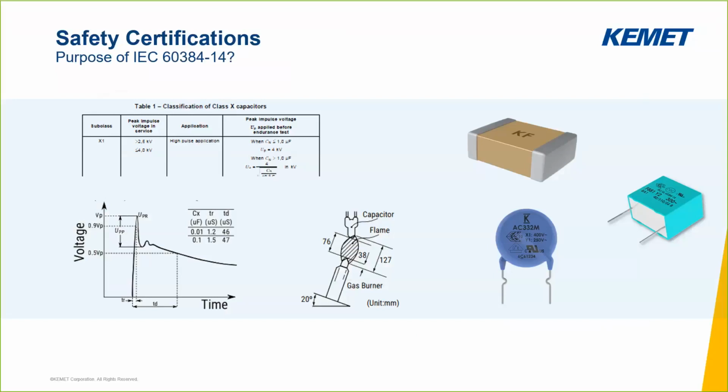The standard also defines the marking for these capacitors, and suppliers must adhere to them in order to certify them to the standard. Some of the markings seen on safety capacitors may include, but are not limited to, supplier trademark, capacitance code, voltage class, and certification body. Smaller disc and surface mount capacitors are too small to print these markings, so the IEC standard provides guidelines on what markings are required.